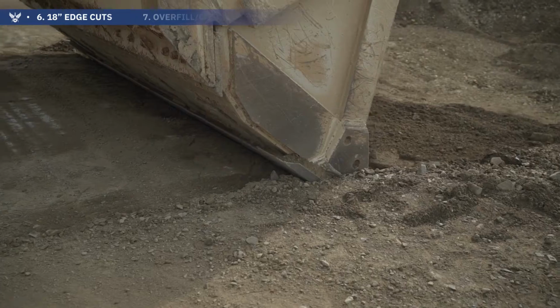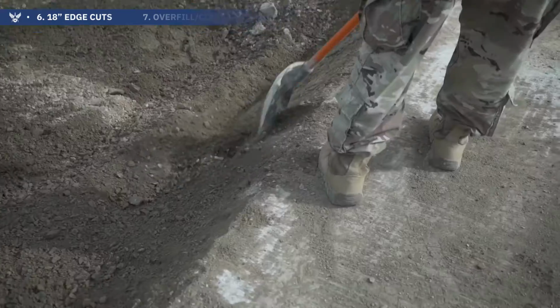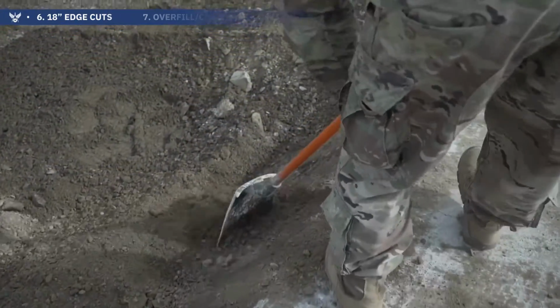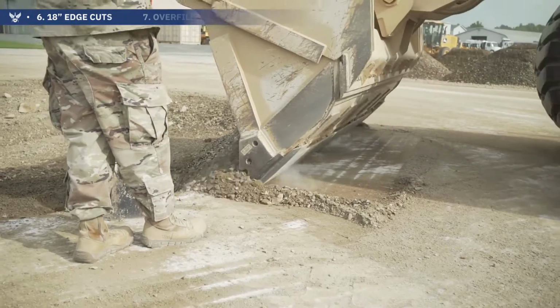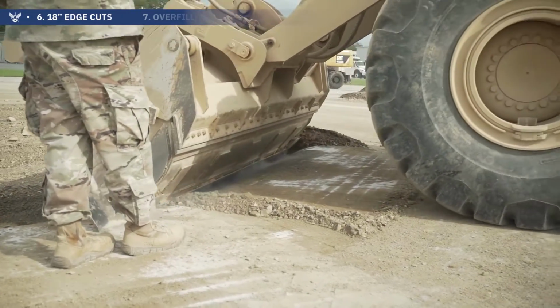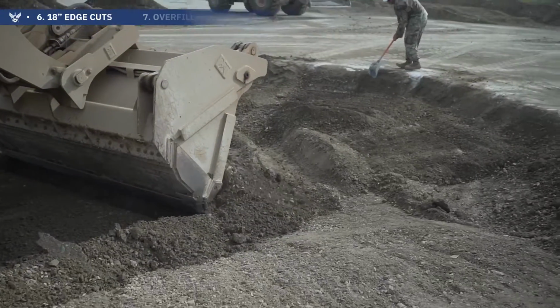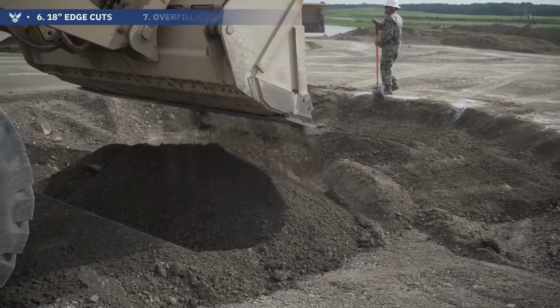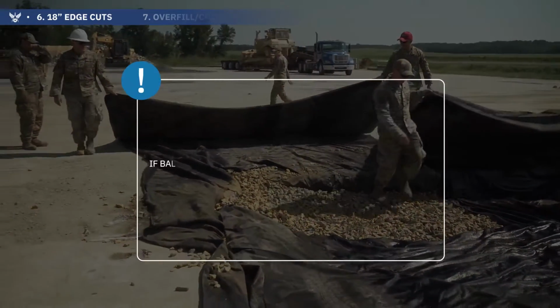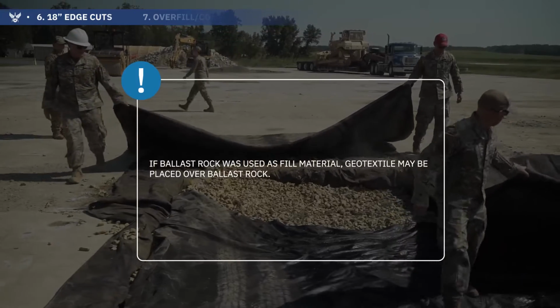Step 6. 18-inch edge cuts and leveling fill material. Make the top 18 inches of the crater side as close to vertical as possible by using the excavator bucket, front end loader, or shovels. Materials cut from the crater's edge can be carried across the crater and leveled a minimum of 18 inches below the crater's lip. Note, if ballast rock was used as fill material, geotextile may be placed over ballast rock.